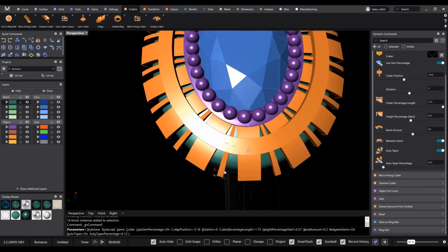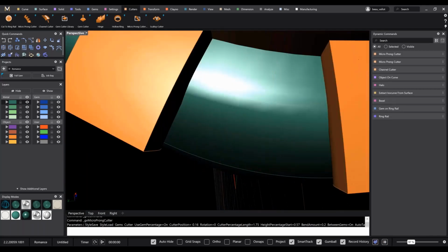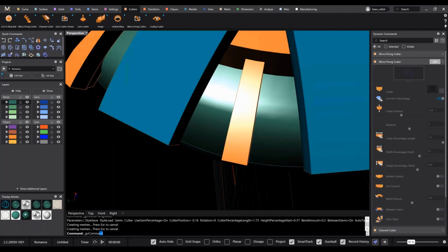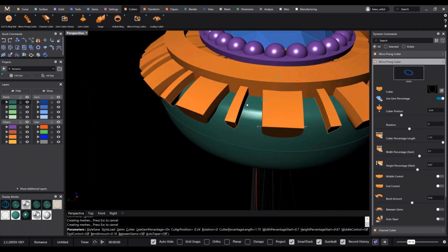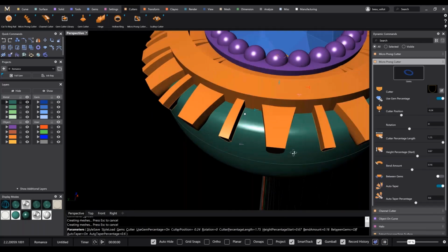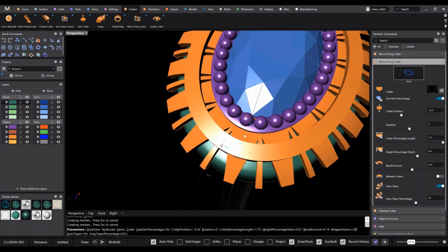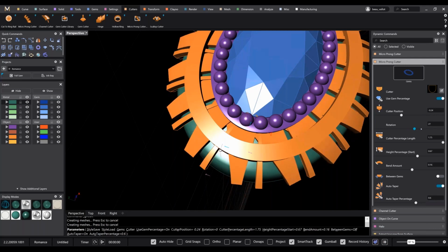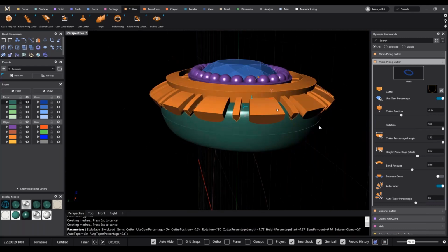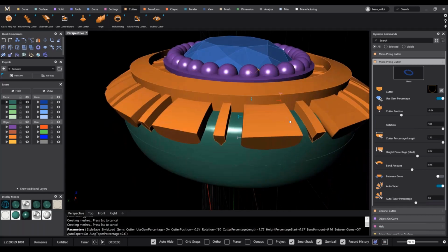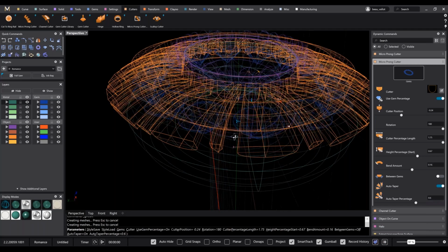And then we can actually go back and edit the scallop cuts to do the same. Toggle auto taper. Now these are facing outside, but they need to face inside, right? So we need to take the rotation and spin them around 180 degrees. Let's go to a wireframe, make sure we're good.